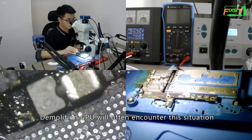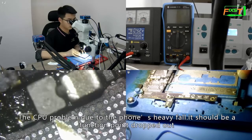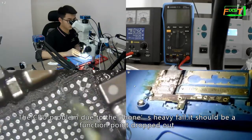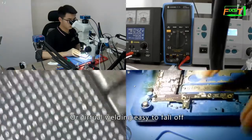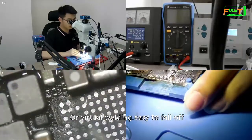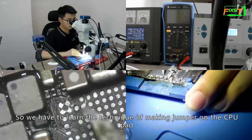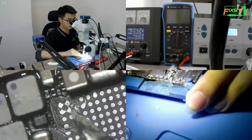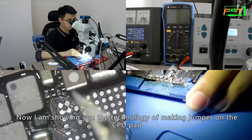When removing a CPU, we often encounter this situation. The CPU problem is due to the phone's heavy fall. It should be a function point drop out, or virtual welding that easily falls off. So we have to learn the techniques of making jumpers on the CPU pad. Now I'm showing you the technique of making jumpers on the CPU pad.